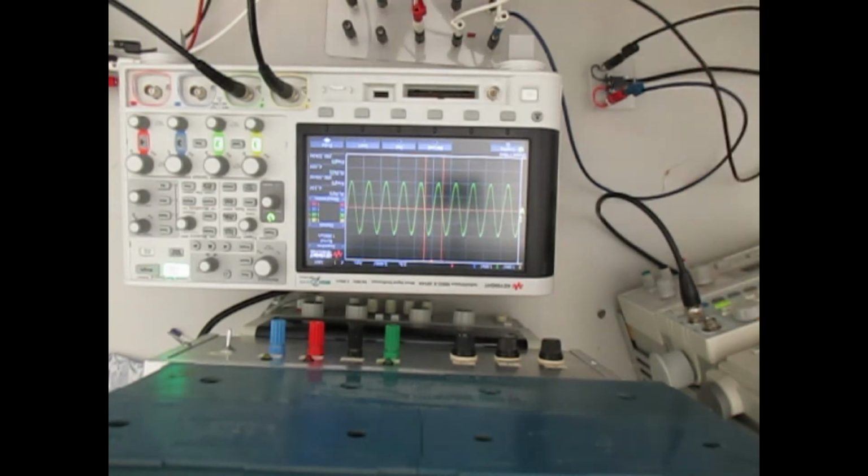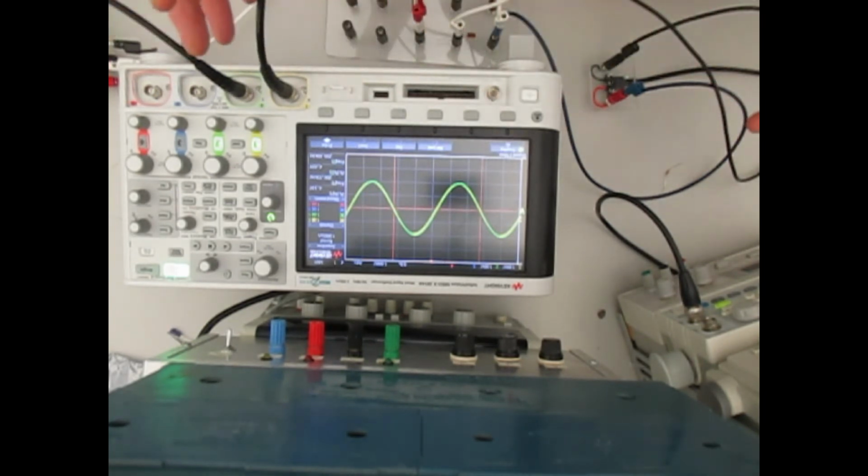Right now I'm at 200 kilohertz, which is more than what we are going to do with our measurements. And you can see now they're almost right on top of each other, right? So now the resistor is way more dominant than the capacitor, and the capacitor is having hardly any effect on the circuit whatsoever. Okay? So anyway, I just wanted to show you the kind of things we're doing in the lab to make these measurements. But I'll provide you the measurements in a spreadsheet.